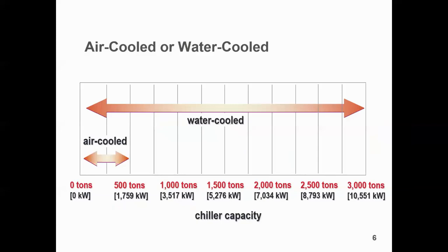This is a typical range of air cooled and water cooled chillers presently available in the industry. From that chart you can understand that for a smaller application we can still use an air cooled chiller, though even for smaller applications we might explore water cooled chillers. But for bigger applications it becomes a mandate, because air cooled chillers are not available, as the footprint of air cooled chillers is quite large. If you go for very high capacity chillers, it is very difficult to accommodate. That's why we had to switch over to water cooled chillers. There are other aspects too, obviously the efficiency part. I'm not getting into that because that's a separate topic, and maybe some other day we can discuss it.